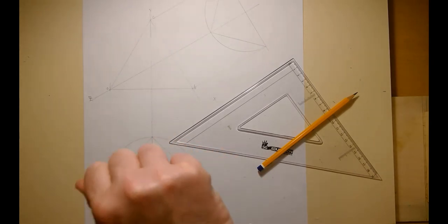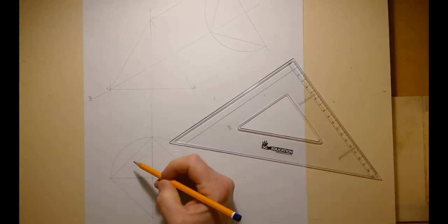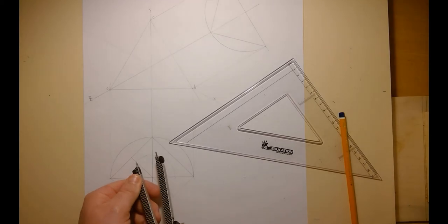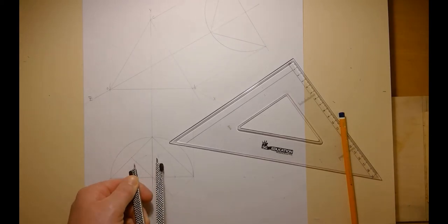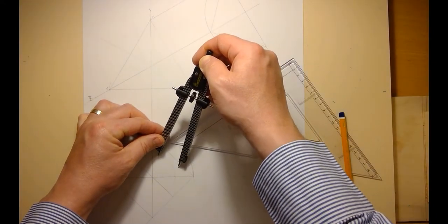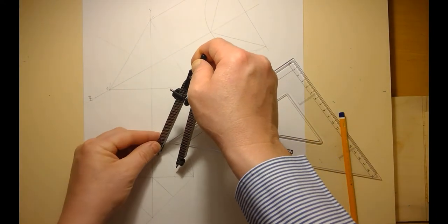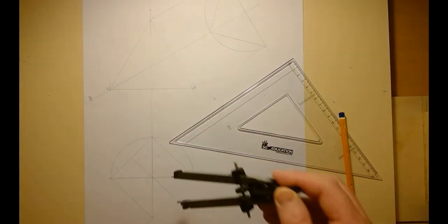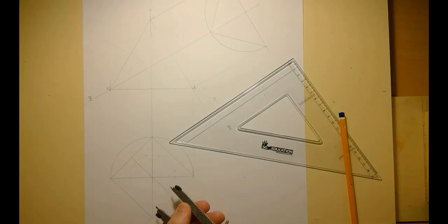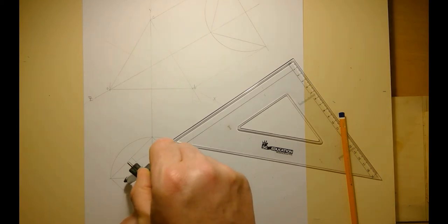Okay, so my hexagon now is going to go around. I know one point is going to be here on it. Okay, so I can use that then from there around to tick off the rest of the points there for that hexagon. Okay, so just keep putting the compass on each point where the arcs cut that circle, and that's going to give me the other points on that one is there anyways. It's going to give me all the other points on that there.